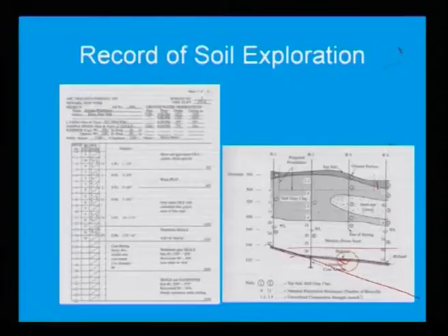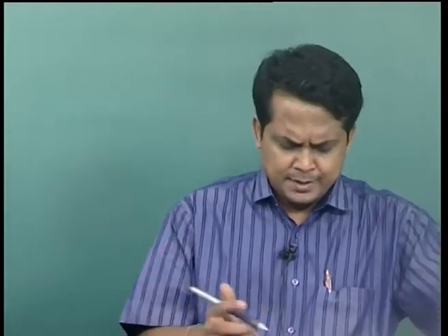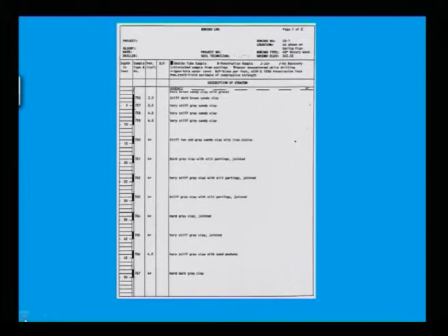No, look at borehole 4. In this grey clay some patches are there where you are getting sand and gravel. Maybe in the 5th borehole the soil profile may be completely changed. It is based on your judgment whether to do or not to do, and how to interpret and give the result, so that the design engineer does not face any problem. This is your first part, as I explained yesterday also.